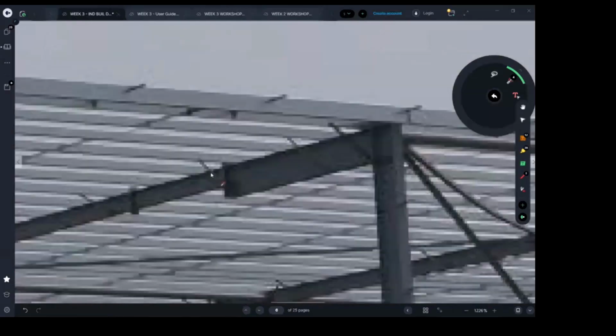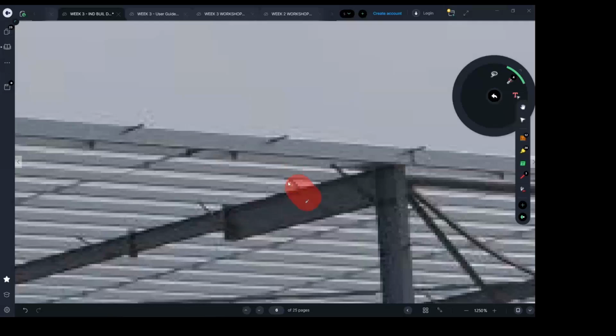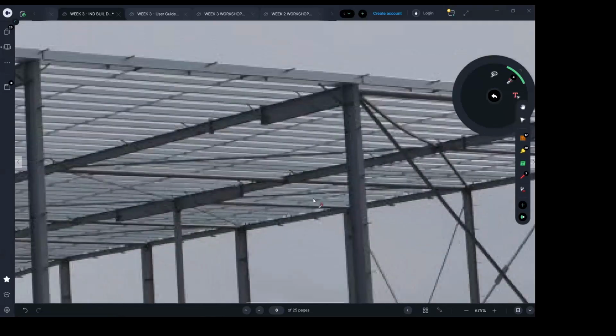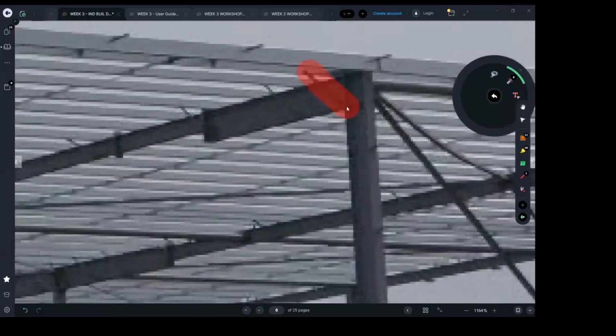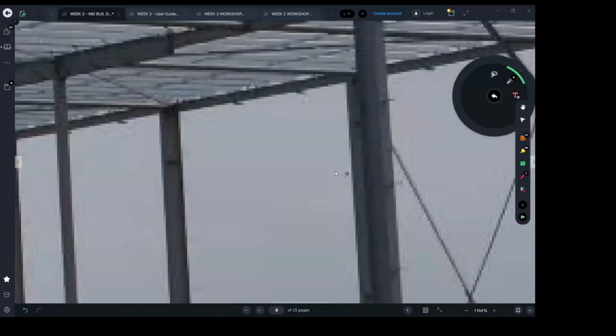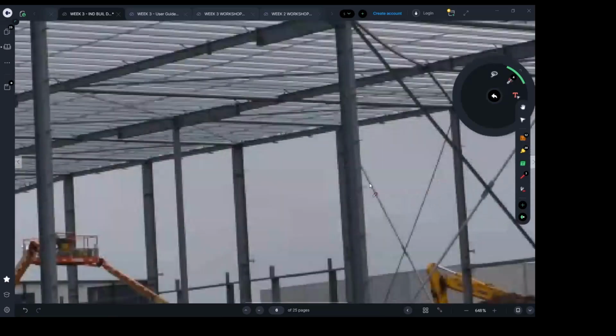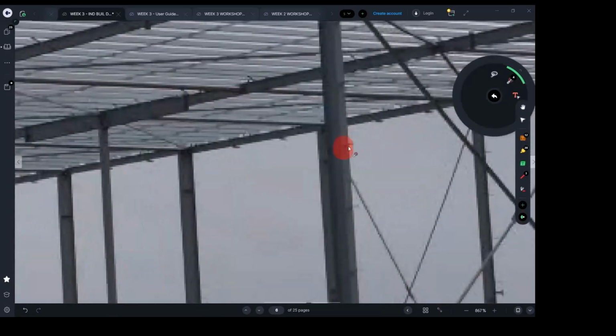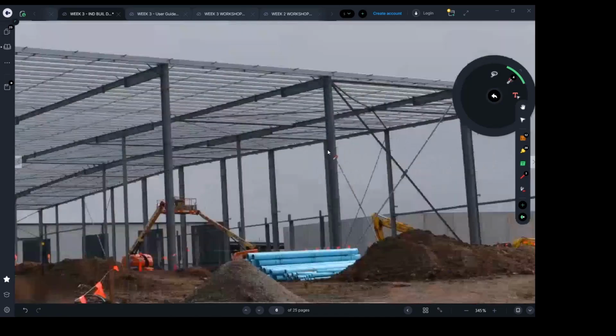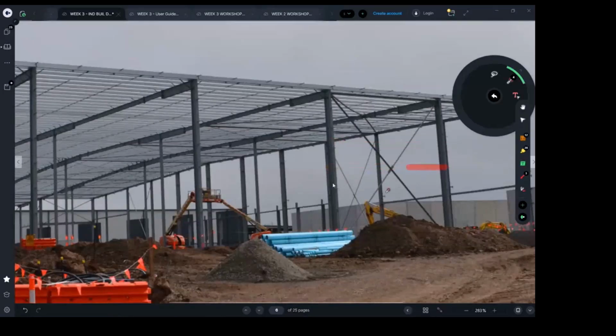These are the bridging, the fly bracing, the fly braces. I think the bridging cannot be seen; I'll show you bridgings later. But here are the fly bracings, which you all know what they do, and you have to know that there are a lot of questions about them. These plates or cleats are the ones which will carry the girts, and the girts will be running through here.